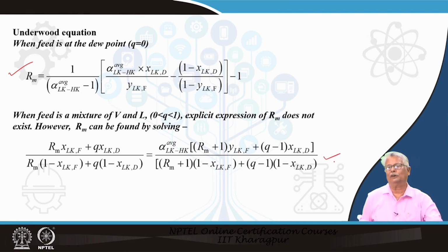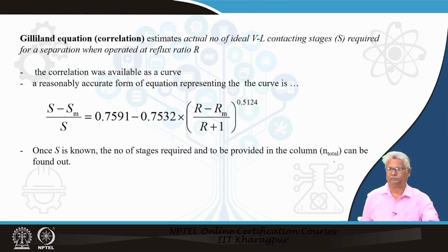So far, we have found out the number of theoretical stages that we have to provide within my tower itself. We also have found out for this particular separation what is the required minimum reflux under a particular feed condition with Q 0, 1 or some other value of Q. The next thing is, we again have something very similar to what we have done earlier.